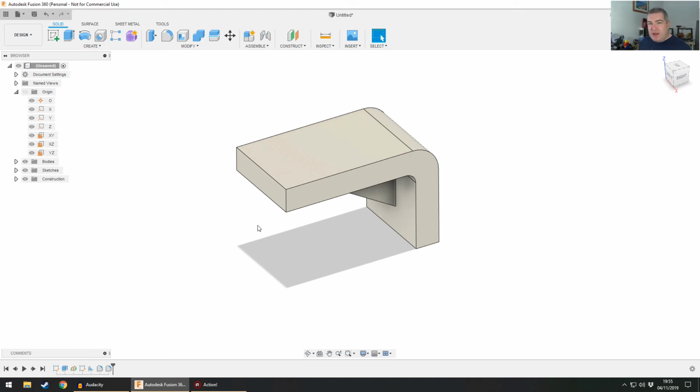It's something that I like to look at when you're looking at a complicated shape. How would you model this? Solid modeling, not surface modeling. Okay, so how would you model that? Well, you would look at creating more geometry than you need in your first extrude. So like a massive block, and then you would cut lumps out of it. That's what the 80-20 rule tells you. Or you could start with the button and then another. No, you wouldn't do that.